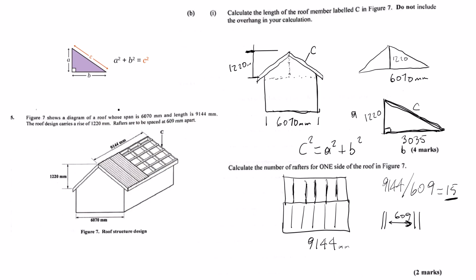And it's not just the length of one rafter, is it? We also need to know how many to use. Correct. And there's a calculation for that too, for the number of rafters on one side of the roof. It's pretty straightforward in this example. How does that work? You take the total length of the roof along the ridge line, which was 9,144 millimeters. Right. And you divide that by the spacing between each rafter, which was 609 millimeters, center to center. Exactly. So 9,144 divided by 609. That gives exactly 15. 15 rafters needed for one side of this particular roof.